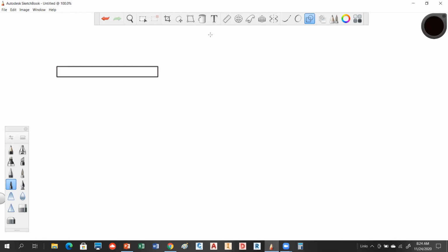Okay, so what kind of board is this? This is a joist. It's a 2x10, right? So we have a 2x10. And the 16 on center have a span of 12.5 feet. Now I'm getting that information from page 418, okay?